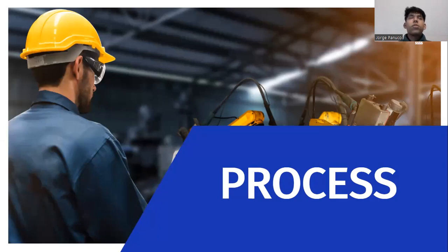For example, you're going to be typing on the matrix keyboard 13A, 4B, 5C. This means that you want 13 kilograms from the container marked as A, 4 kilograms from the container marked as B, and 5 kilograms from the container marked as C. All these will be dispensed to the reactor, where they will be mixed with the help of a small motor to achieve a homogeneous mixture.